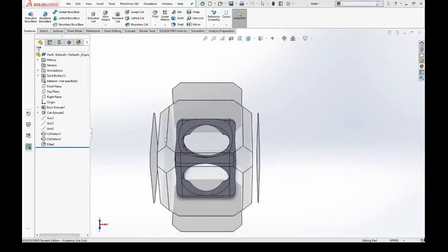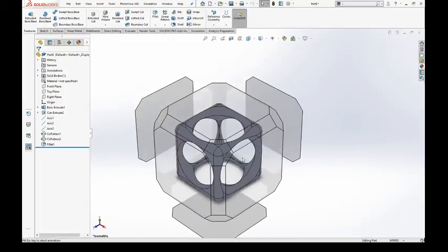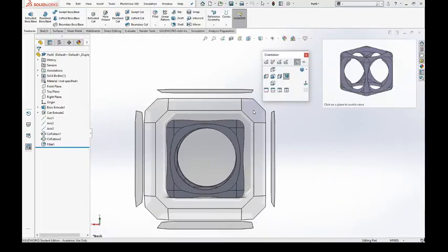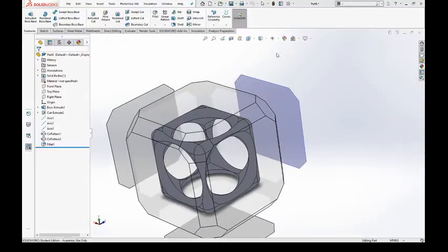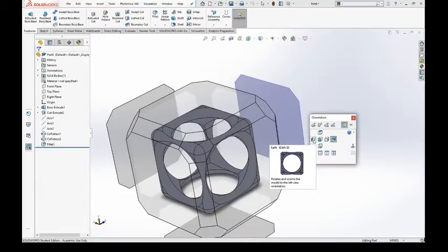Press the spacebar again, I could pick another part of this view cube and it would look from there. Okay, I could choose one of these planes and it would look from there. However, I can also choose to use this box as well, and if I hover over each one of them, it tells me the front view is control 1, control 3 is left view, top view is control 5. Okay, so there's lots of things to look at here.